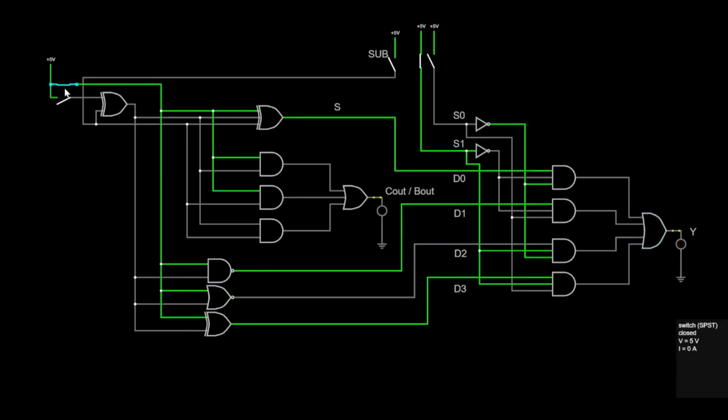And of course, if we change this to 1, 0, you can look at the NOR, because we can see where the data line is currently selected, selecting D2 or input 3. You can see that when we put 1 and 0 for A and B, and we select the NOR operation, the NOR operation travels to the multiplexer into the 4 input OR gate and out here, but in this case it's a 0, so there's nothing actually going that way.